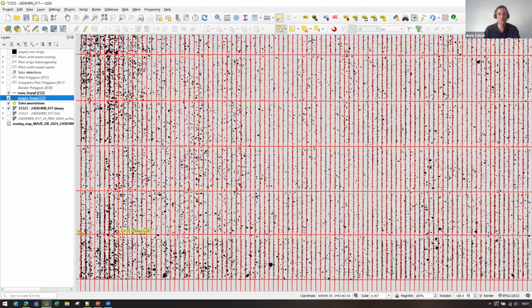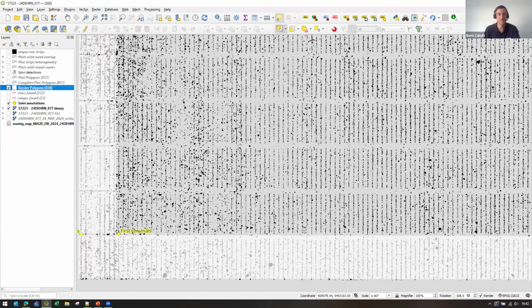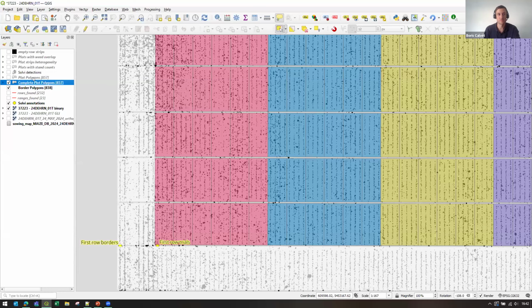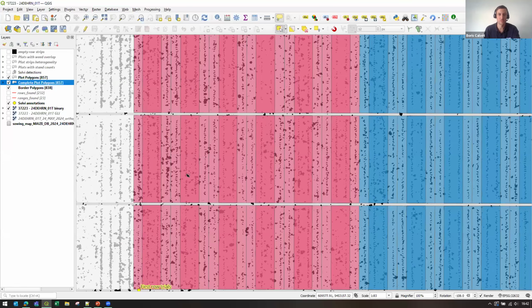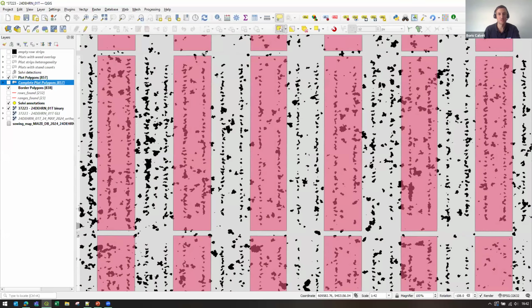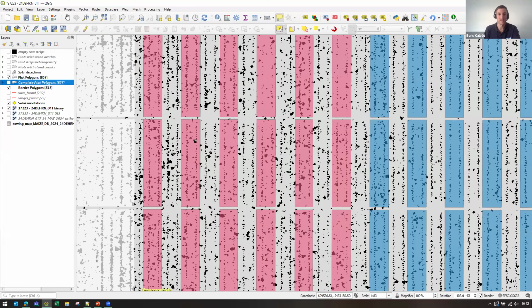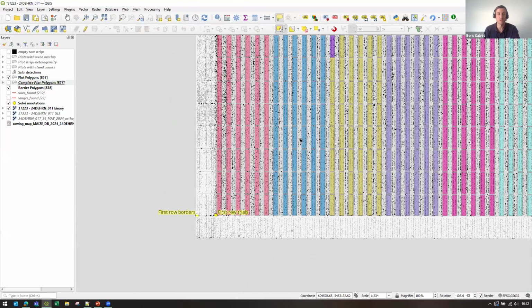Once I have these two and I have the list of plots coming from my database, I can place the border plots. I can also place the experiment plots, and you'll see, for example, on that field, we have one of the specific plots. For the 4-row plots that we have here, we are actually interested in only the 2 central rows. So the final polygons I will be using are these ones. And this is what I will be re-uploading to Solvi. This is what Igor was showing you on his field too.